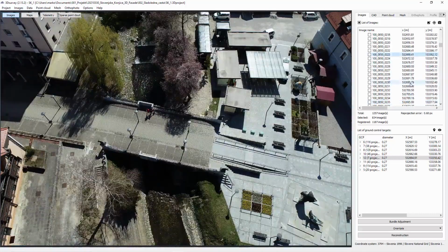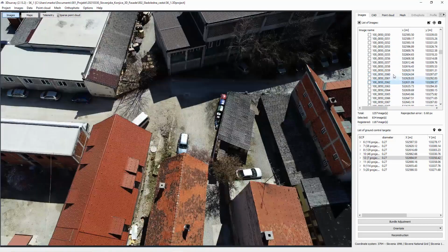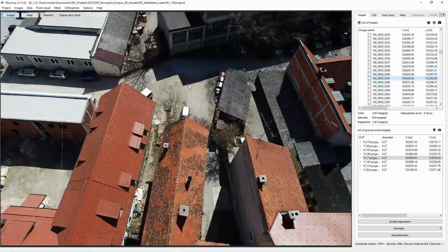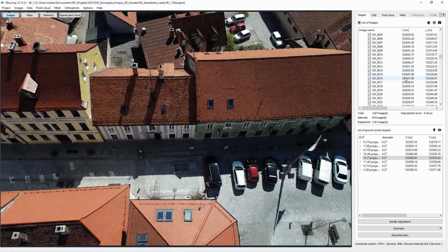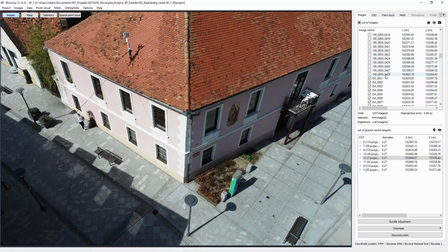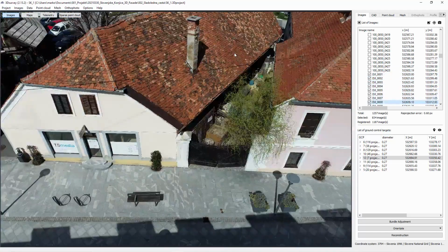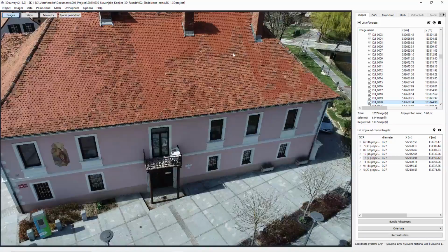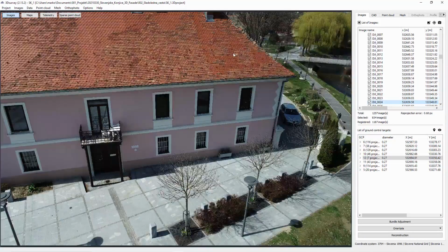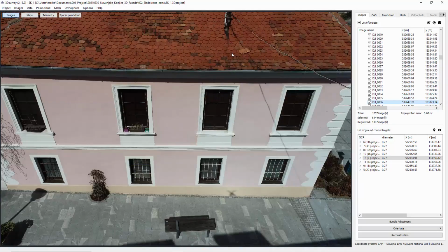And then when I start with my manual flights, let's go a bit further down. Here we are still okay. I think no, still double grid. Okay, here we can see by the name. So this was the planned flight mission, and here DJI 001 is where I start with manual flight. And as you can see, I try to fly parallel to the road, turn the gimbal angle to, let's say, 45 degrees or something like that, and just trigger images every 2 seconds or so.